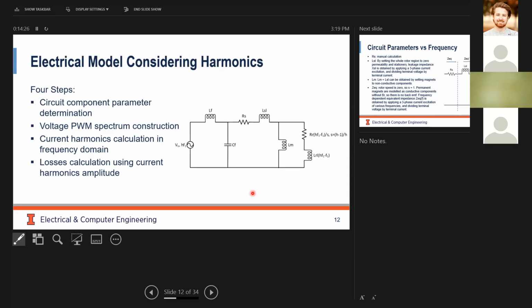Okay, so on the right is the equivalent circuit we just developed, and on the left-hand side is the drive. The drive is not a single sinusoid. It's a combination of multiple sinusoids, starting with the fundamental harmonic, with an order of 1, the first order, and then there will be second order, third order, fourth order, etc. So this is not just one circuit.